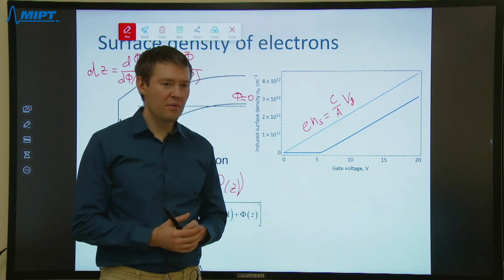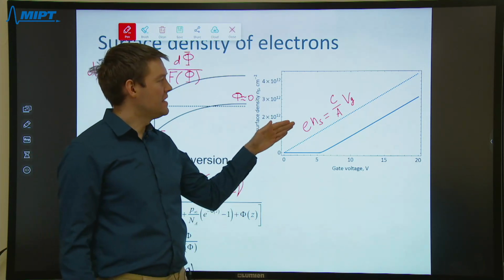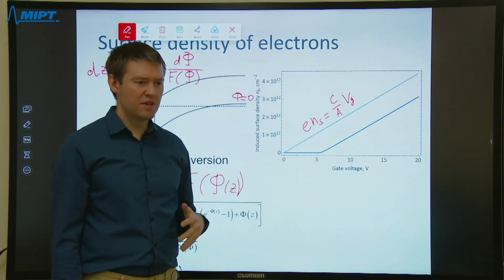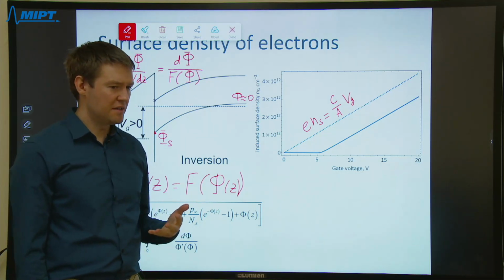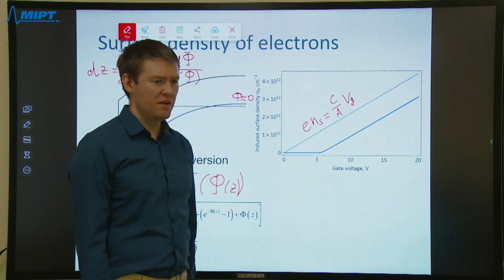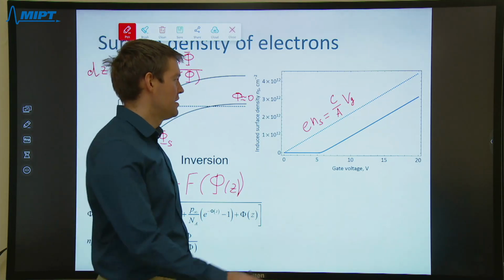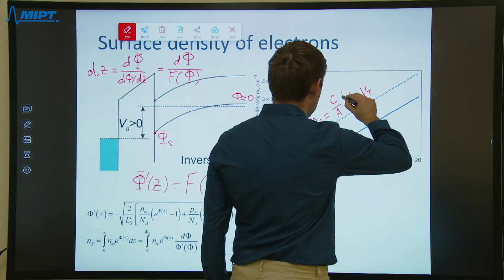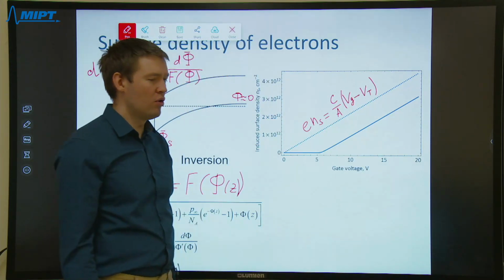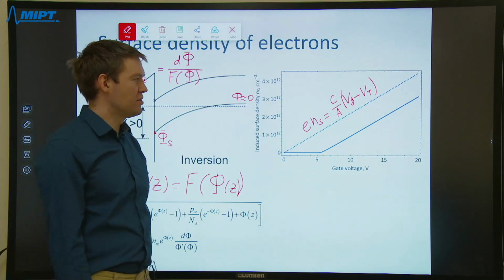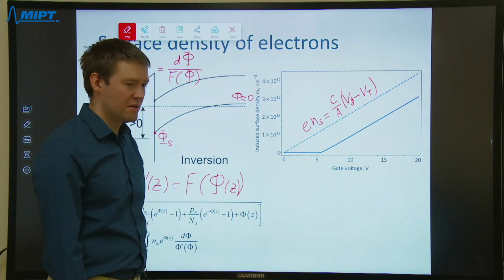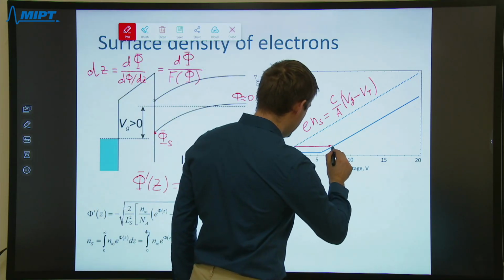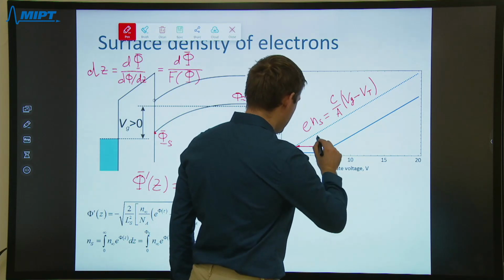So our old theory doesn't predict a range of gate voltages that corresponds to the off state of the device, but it can be fixed in almost one phenomenological step. We can add some threshold voltage, Vt, corresponding to the switching on of the transistor, that places the approximate theory onto the true theory.